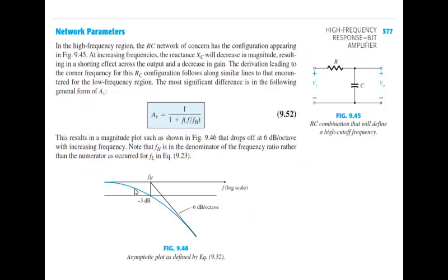So this is figure 9.46. This is the asymptote which indicates a roll off of minus 6 dB per octave above cutoff. So these two cutoffs would be indicated as fHi and maybe here fH naught. So another roll off you will get at this point, depending upon which frequency is higher. If fH naught is higher than fHi, then it would lie ahead of fHi.